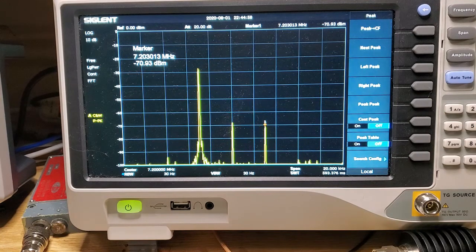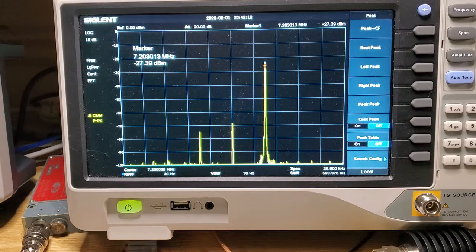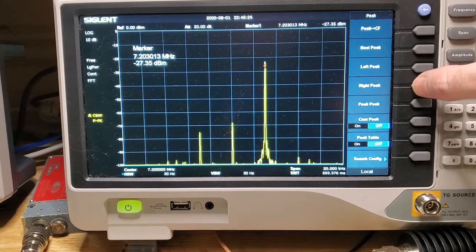I can change that upper and lower sideband relationship just by simply changing the left and right channel coefficients in the software. So I'm not touching the circuit here. I'm not swapping any cables over. Just swapping the coefficients over in the code, and you should see now, when it comes back, now we've got the upper sideband, and it's got the same level of attenuation there.